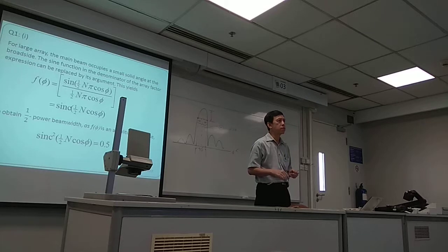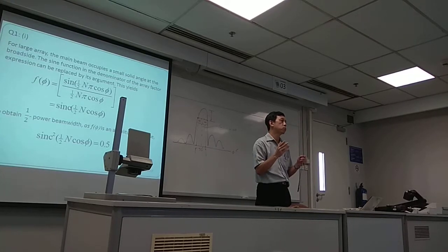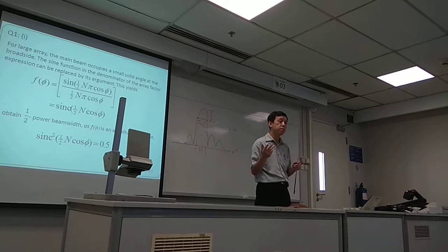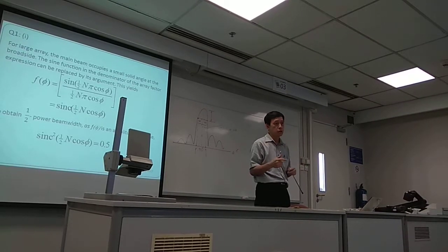You have all done that before, right? I think you have all done sampling theory, right? At least from the second year. So you know that you have to have your sampling frequency to be at least twice that of the maximum frequency value of whatever components in the signal.